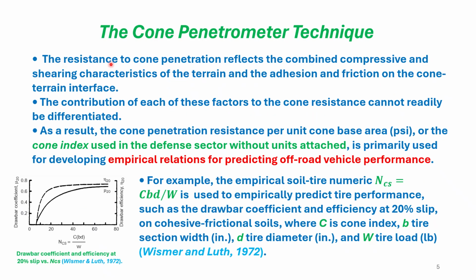The resistance to cone penetration reflects the combined compressive and shearing characteristics of the terrain and adhesion and friction on the cone-terrain interface. The contribution of each of these factors to the cone resistance cannot readily be differentiated.